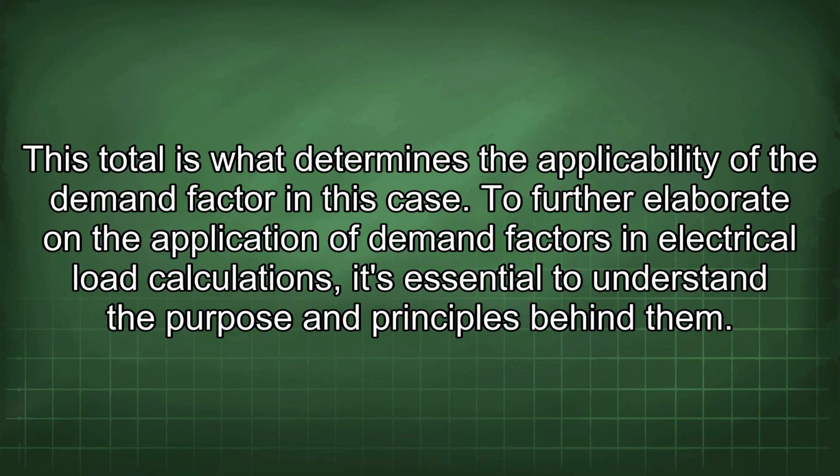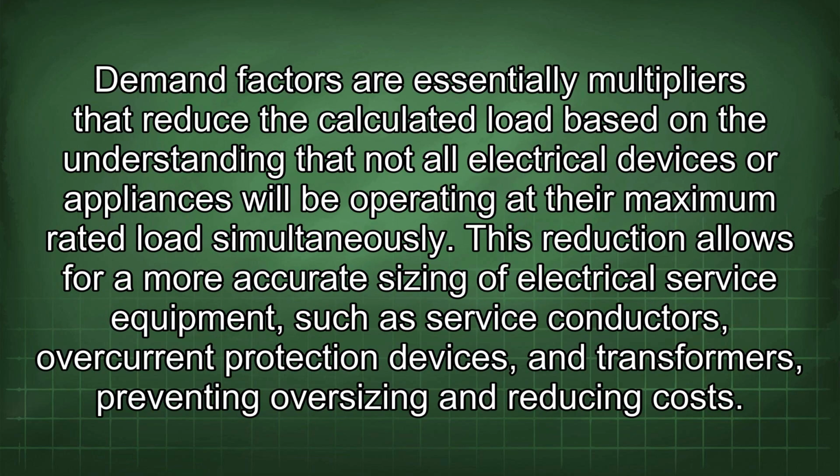To further elaborate on the application of demand factors in electrical load calculations, it's essential to understand the purpose and principles behind them. Demand factors are essentially multipliers that reduce the calculated load based on the understanding that not all electrical devices or appliances will be operating at their maximum rated loads simultaneously. This reduction allows for a more accurate sizing of electrical service equipment, such as service conductors, overcurrent protection devices, and transformers, preventing oversizing and reducing costs.